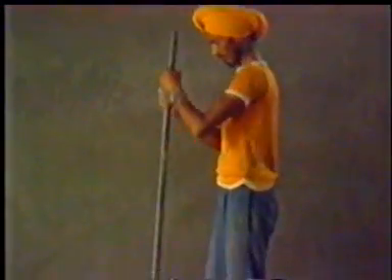Concrete flooring. Before laying the floor finish, a sand cushion of required depth is laid and then compacted by ramming. Lean concrete is laid over the sand layer and leveled. Levels are marked on the side walls for providing appropriate slope in the flooring.